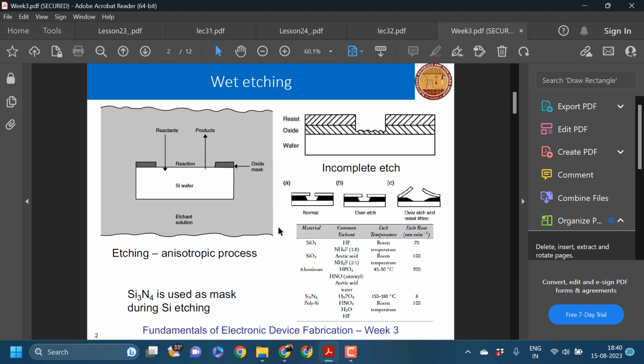Yeah. One thing is when we are not allowing sufficient time for the etching process to take place. Another is when the concentration of the etchant is not sufficient, or when the temperature is not sufficient. Other defects associated with wet etching include over etching and under etching. Over etching means that part of the photoresist will also be stripped, that is when we are allowing too much etching time. And under etching means that all the places are not evenly etched.